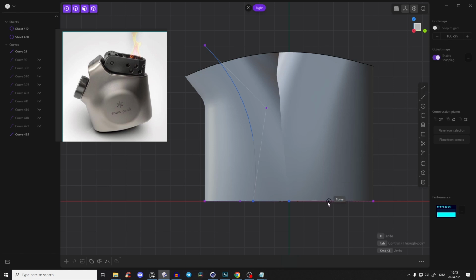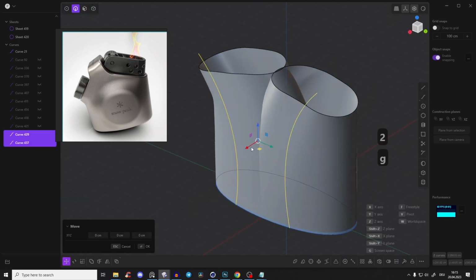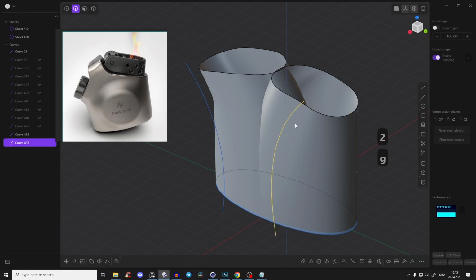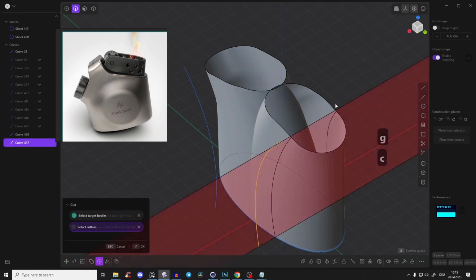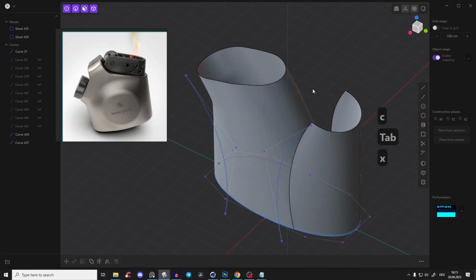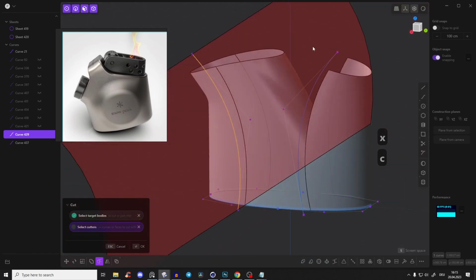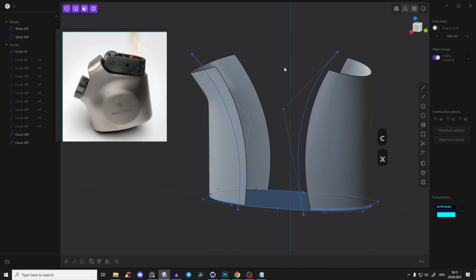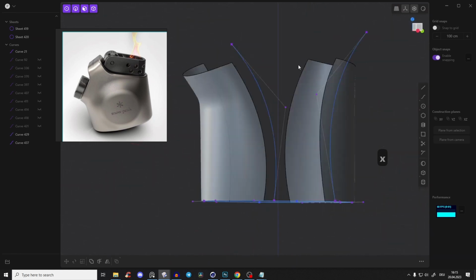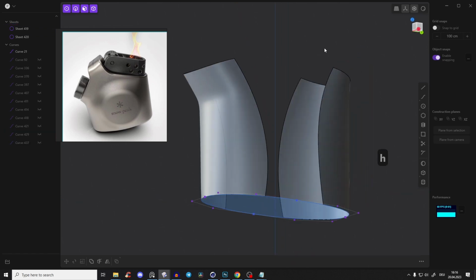And the same on the other side, we will just cut it somewhere like here. And yeah, cool. So let's just drag them outwards a little bit. So let's select this curve, C, and cut this body here. And we can basically delete this point, face. And also we select this curve, press C and cut this body here. Right click and again delete it with that. Perfect. So you see we have something like that. We can hide those curves here. So that looks already cool.